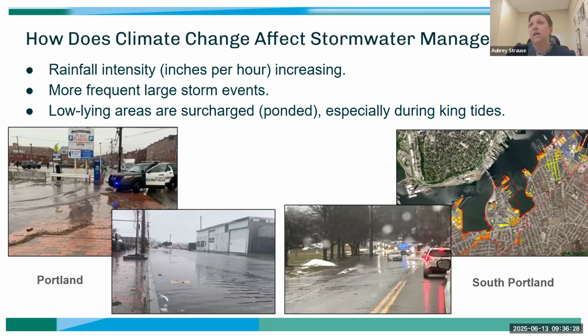One of the things we can do is insist that with new development and redevelopment, whatever the proposed project is, it needs to not send additional water into our systems. We need to keep all their stormwater on site. Is that going to increase construction costs? Yes, and that's a challenge. A lot of developers say that's not fair to make us put in these storage systems and these subsurface chamber systems. They're expensive. I can't do my project if I have to do that. So that is part of that balance that has to happen between economic development and stormwater management.